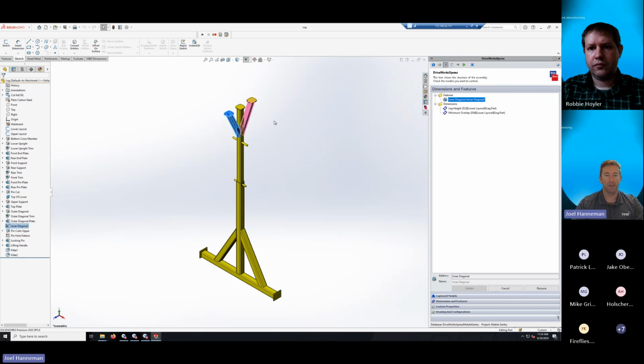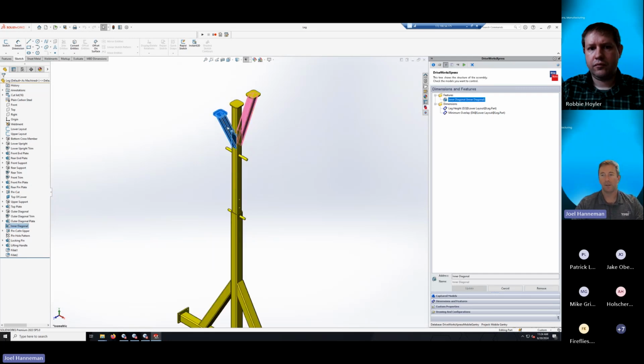One is this little support structure. So this is a feature in SolidWorks. Any old feature you can capture just like this. And just fast forwarding a bit, what is configurable about this feature is it's either there or not. So in modeling terms, it's either going to be suppressed or unsuppressed, just to keep it simple.